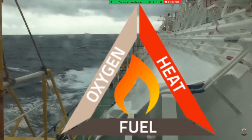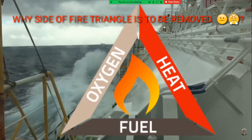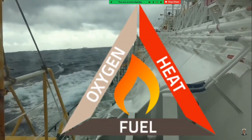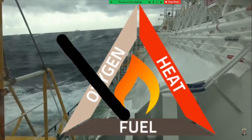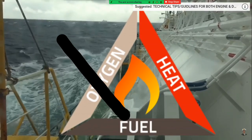But the question is, which side of the fire triangle should be removed? The best possible way is to remove the air part of the triangle, that is the oxygen. We can remove it by simply inerting the atmosphere of the tank.